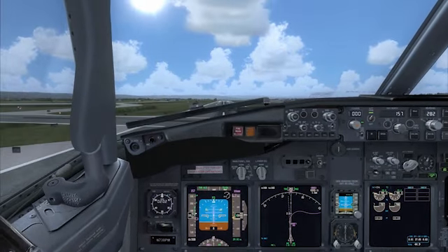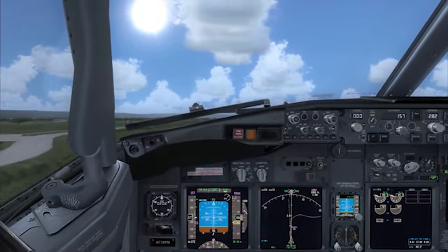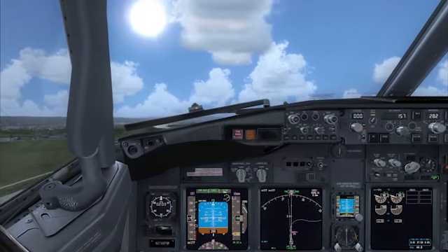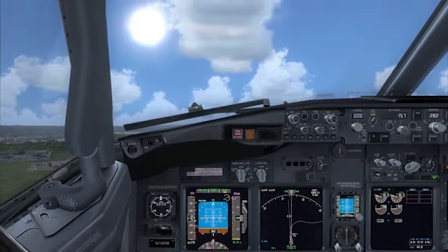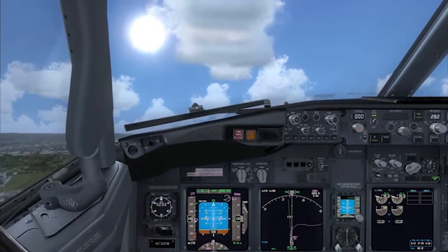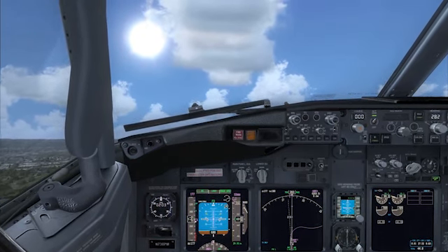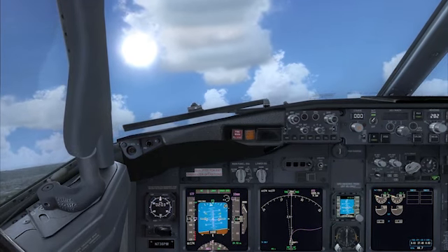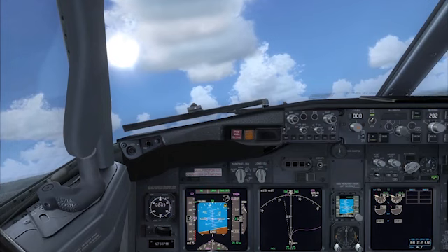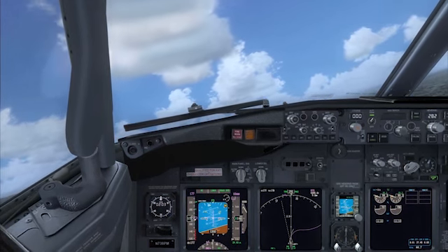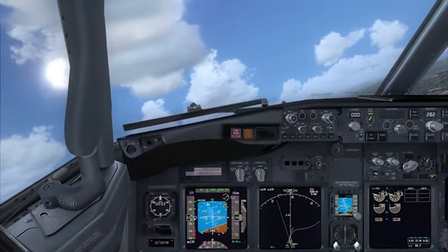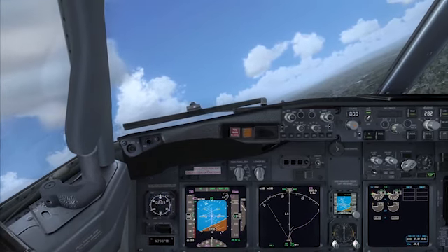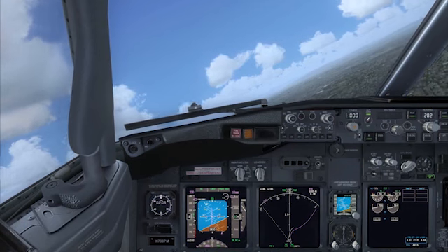In certain situations, for example on takeoff when autopilot isn't available, the flight director is available. Although takeoff is largely a visual maneuver, the flight director will give commands until the autopilot can take over at 800 feet AGL. We'll be using the flight director often in all hand-flown situations when we're in flight work and line work, where you'll learn to become very familiar with mode selection via the MCP and autoflight guidance via the flight directors.